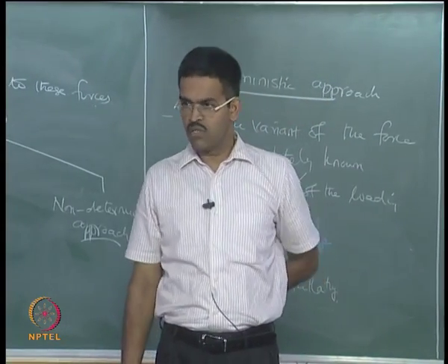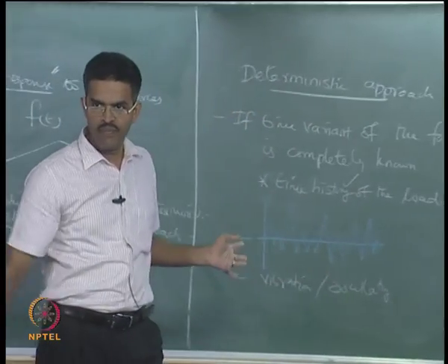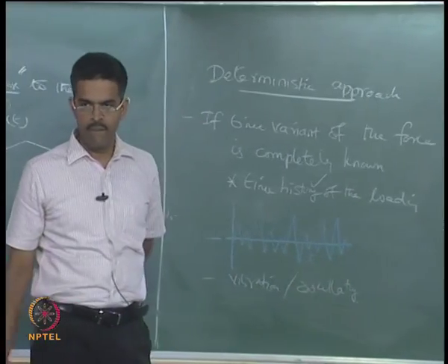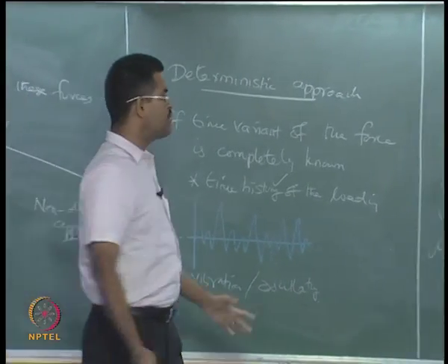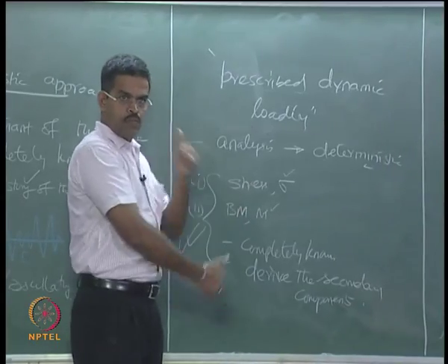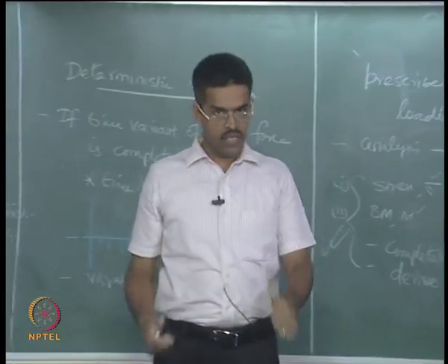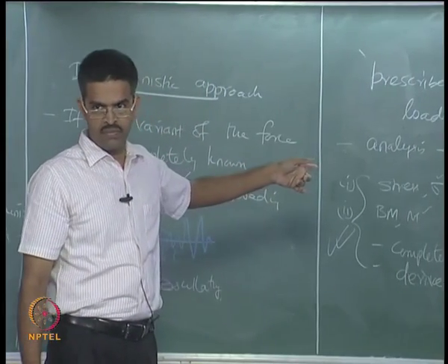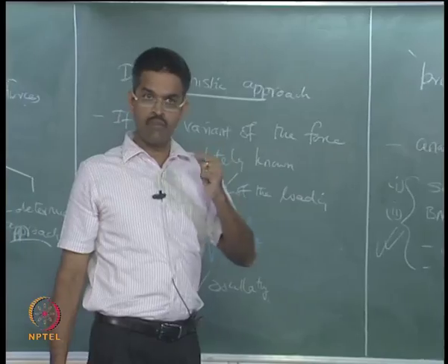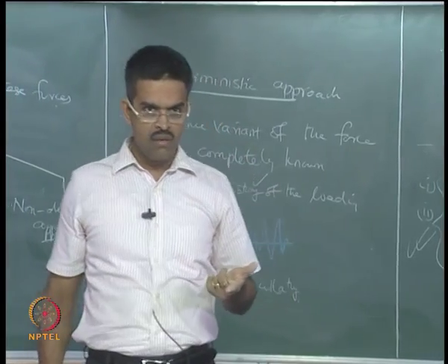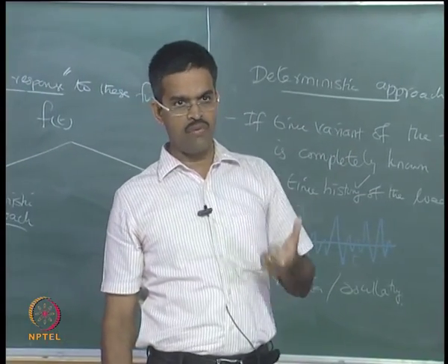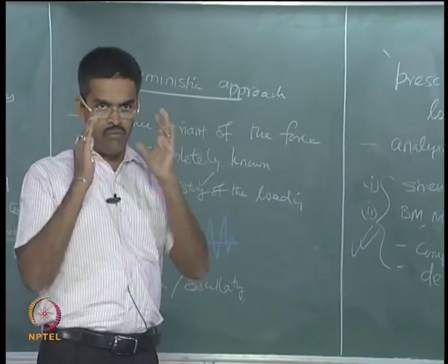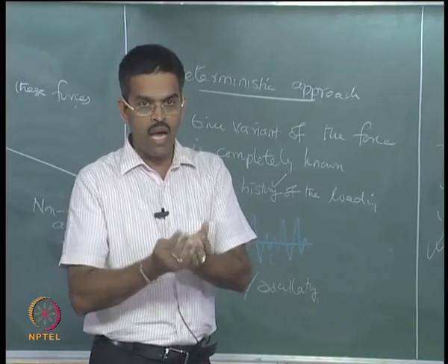Okay, it is faster. It is also dynamic analysis. Why is it a dynamic analysis? Yes, you have a time varying content present in this, which is one of the important components of dynamic analysis. It is a dynamic analysis, right, but the approach is deterministic. The structure may not be determinate, understand the terminology very carefully. The structure may be indeterminate, the approach is deterministic because it is my view, I am looking at this problem as a closed form solution.